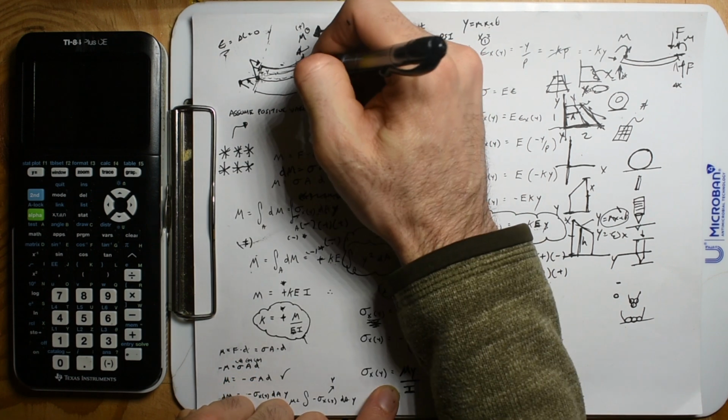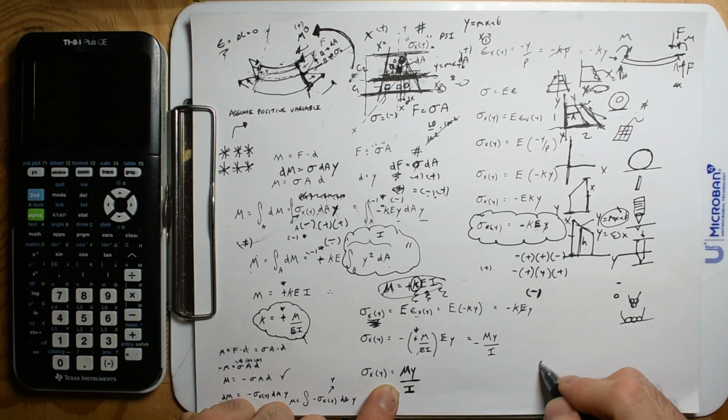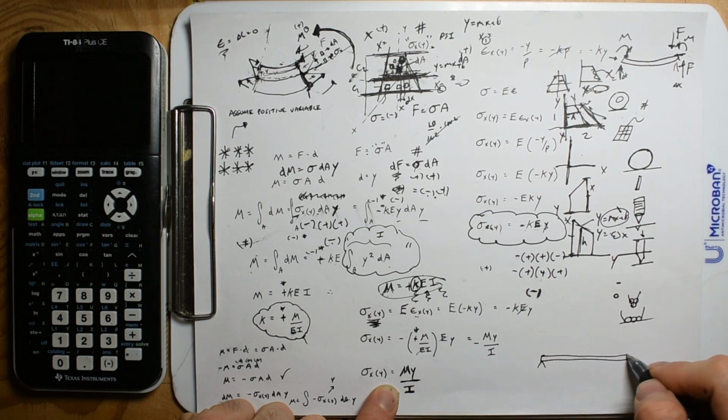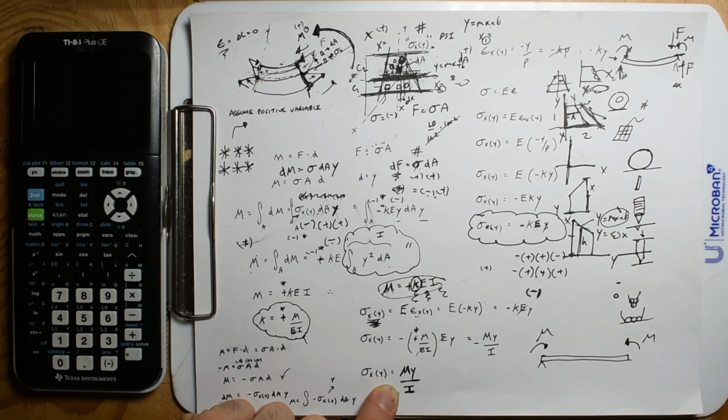And the internal moment right here, we see that it's due to the forces. When we do just a beam, and we throw a moment right here and a moment right there, in this situation, if the beam is negligible weight, there's no load, there's no resultant there and there. There's no shear forces. There's no axial forces. Those are all zero. And so any free body diagram chunk, we have a moment generated there.